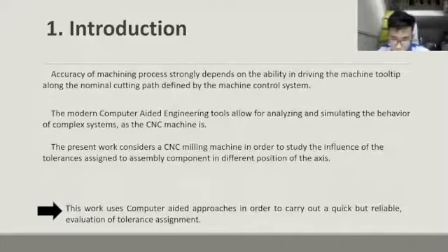tooltip. Broadly, machining errors depend on two major error sources: motion errors of the machine tool system, and errors due to the machining process. Major causes of errors in the machine tool system include imperfection and misalignment of guideway of sliding stage. The assembly errors of the alignment of each axis, the non-parallelism of guideway, and profile errors of guideways affect the accuracy of three-axis machine tool.